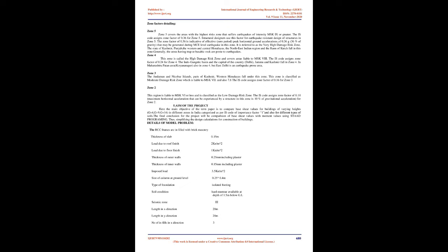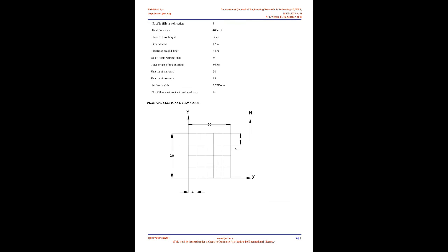12. Importance factor. It is the factor used to obtain the design seismic force depending on the functional use of the structure, characterized by hazardous consequences of its failure, its post-earthquake functional need, historic value, or economic importance. Important service and community buildings, such as hospitals, schools, monumental structures, and emergency buildings like telephone exchanges, television stations, radio stations, railway stations, fire station buildings, large community halls like cinemas, assembly halls and subway stations, and power stations.